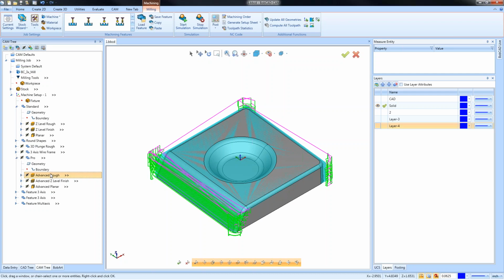Is the non-center cutting option stock driven or geometry driven? It's stock and geometry driven. Stock driven, so it knows where to start from, Scott, and geometry driven because it needs to know whether it has to plunge in an area or not. So when you say it's non-center cutting, it needs to look at the part geometry and know whether it's plunging or not. So it's actually both stock and geometry driven. Hopefully that answers that question.